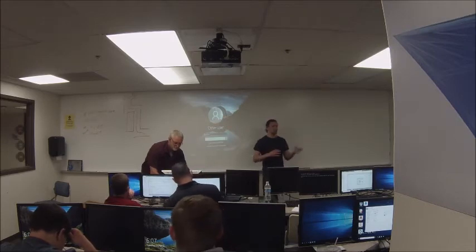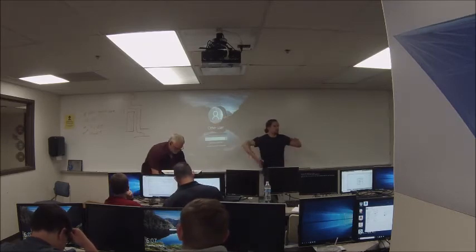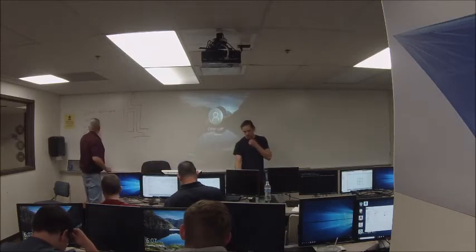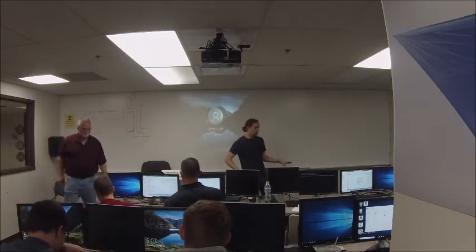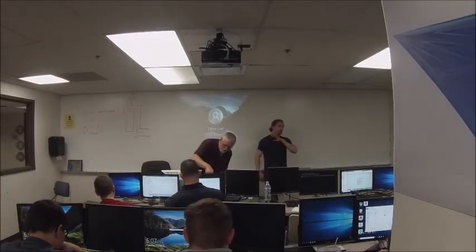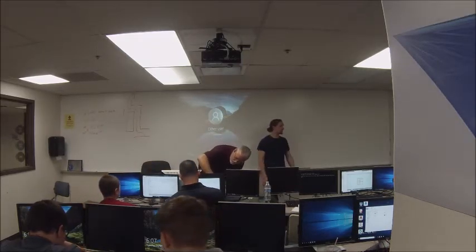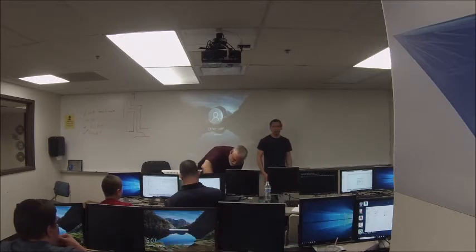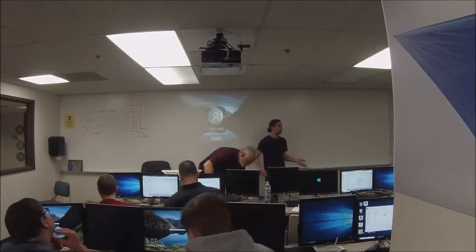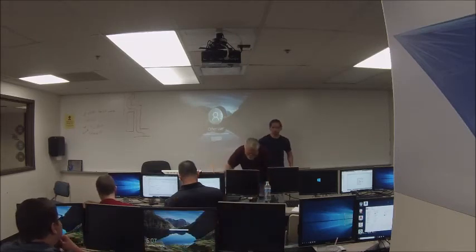So it's kind of like a skid steer or a tank where you're driving 2 sides independently, and that's how you maneuver. They can be 4-wheeled, 6-wheeled, or 8-wheeled. There's a lot of different types of wheels that you can use. We'll talk about different types of wheels in a later class because deciding what wheels to use in the drivetrain is a big, important part of the design process. They have a lot of advantages and disadvantages.